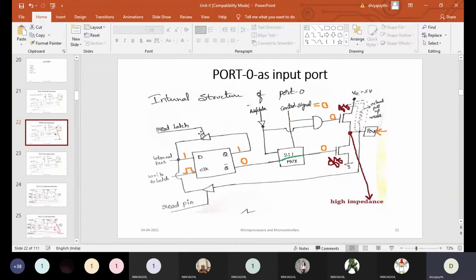Then what is the difference between the buffer and the D flip-flop? For the buffer, nothing is required to take the input as an output. Whatever input you give, it takes it by default and considers it as an output. But here, to make sure that whatever input it receives becomes the output, the D flip-flop should be enabled by a clock signal. Enabling means that even though you are providing your input at this particular D pin, if you are not giving the clock signal, then you can't see the output at the Q pin.